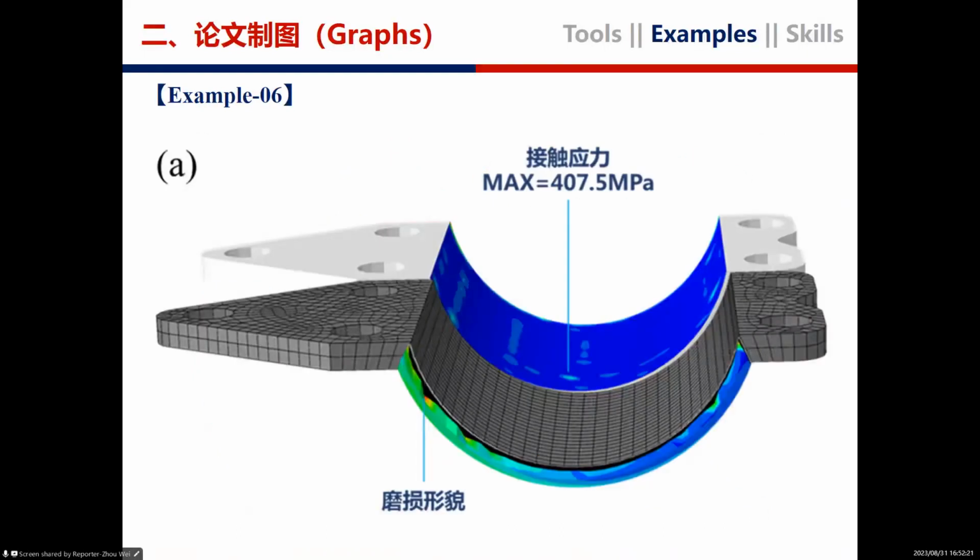We also use 2 sets of pictures to respectively denote the contact stress distribution on the bushing gear's inner face and its aberration compared to the undamaged profile by using its gray-colored mesh model and its contour map of deflection. So, although the displacement is exaggerated, it does tell a very clear view of how the inner face is damaged due to vibration. As you can guess, this graph is totally created in PowerPoint. The image materials are from the finite element analysis results.